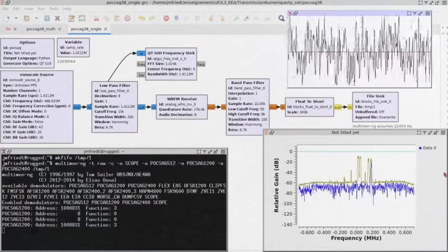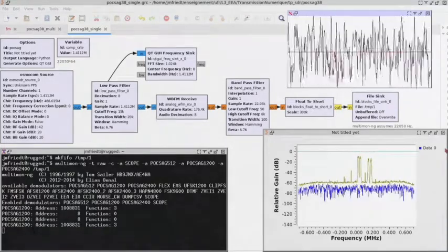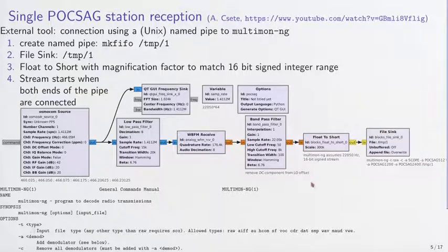This is the last message that has been transmitted before stopping this analysis. So we see here that this bandpass filter acts as a zero crossing detector. Otherwise, the output here of multimon would be offset, the voltage output would be offset, and would prevent the zero crossing detection, which marks the beginning of a new bit transmission.